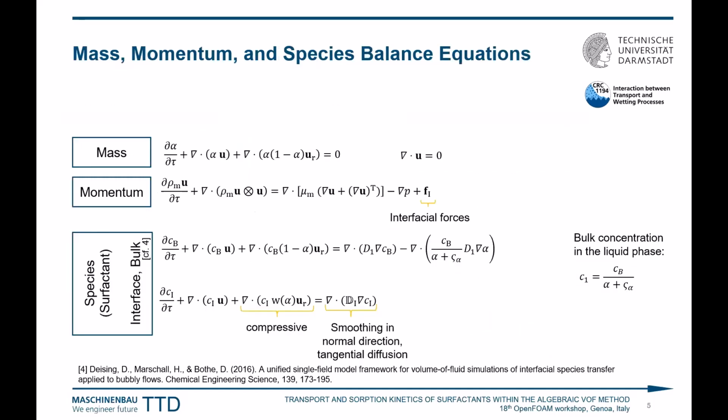Then coming to the numerical methodology, as you all know, the mass conservation equation consists of both the scalar advection equation for the volume of fluid combined with the continuity equation, followed by the momentum equation with all the regular terms and the body force term, which also includes the interfacial forces term. Here we have dominantly the surface tension force, but also in some cases, if needed, a collision force or wall contact force, all these can be implemented.